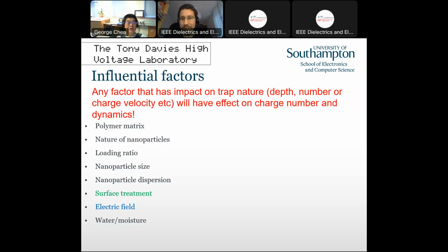Hopping is one of the mechanisms contributing to the DC conductivity. Yes, they are related, but there are some other mechanisms as well. Maybe I can add something. When people consider nanomaterial or micro level layer material, there are different kinds of conduction mechanisms that can happen, under the umbrella of DC conductivity or DC conduction mechanism, and hopping conductivity is one of them. So it can be hopping or trapping or space charge conduction mechanism, or there might be the Schottky emission,